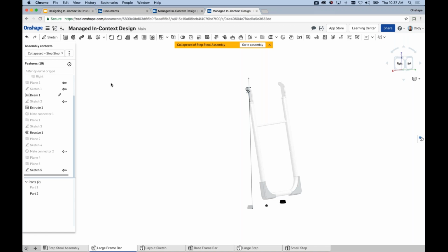And if all you have is context 1, 2, and 3, it may not be as clear what they are. But if you name them open, closed, position 1, position 2, it makes it easier to update later because they correlate. So again, renaming your context makes sense.